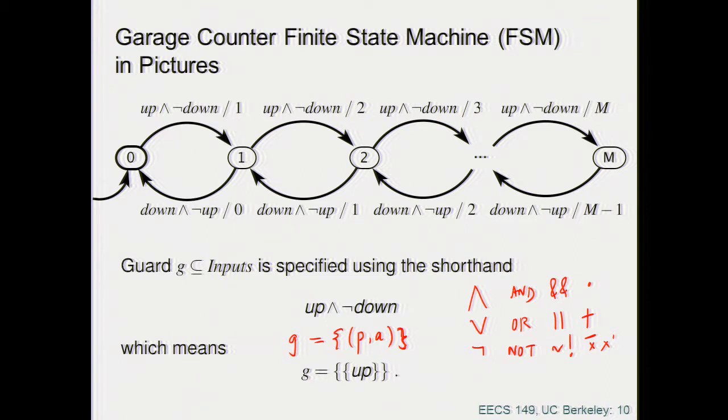Now, what will be the label that is associated to this moving from one state to the next? What is the reason why I'm changing one state to the next? It's because there is an action. I'm reacting, so there is an input. The input is the trigger of this change of state. In fact, these arcs carry a label that says under what condition I go from here to there.